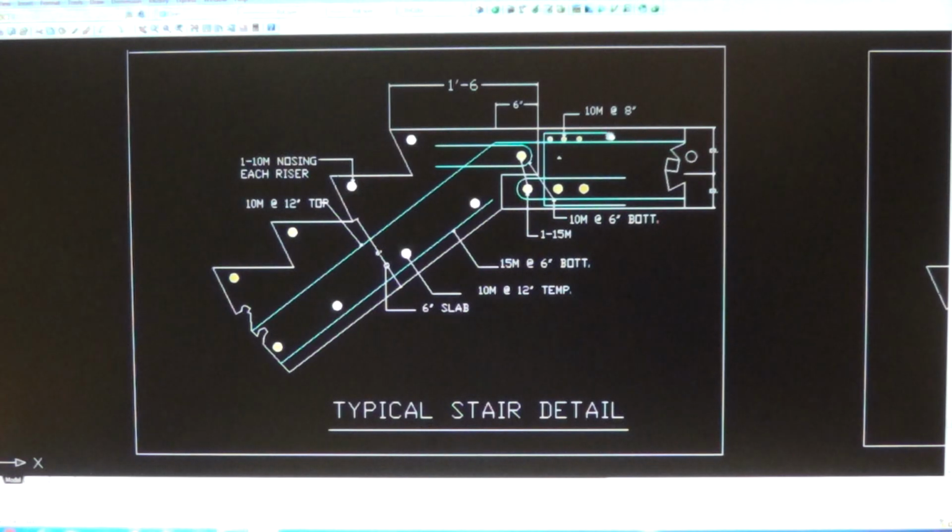You have to install a square dowel enclosing all the bars. Okay, this one here is like a square dowel enclosing all these bars at the top and the bottom. And pay attention to the hook there, the development length of these bottom bars, and the development length also is 180 degrees for the stairs portion. This is the connection in between the landing and the stairs.